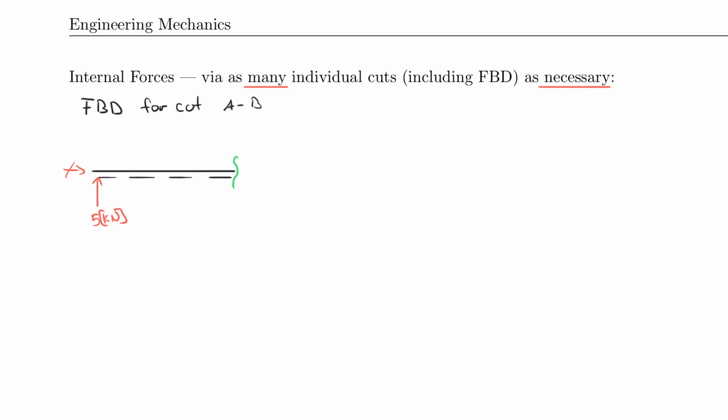And what I do next is I will bring in my internal forces that therefore become external forces. So for example, I use my little study card, which tells me that the moment goes in this direction, the shear force in that direction, and the normal force goes in that direction. So I now indicate them, and I call them M at B, V at B, and N at B. And you can already tell that due to the sum of the forces in the x direction being equal to 0, N at B is really equal to 0. I don't have to explain that.